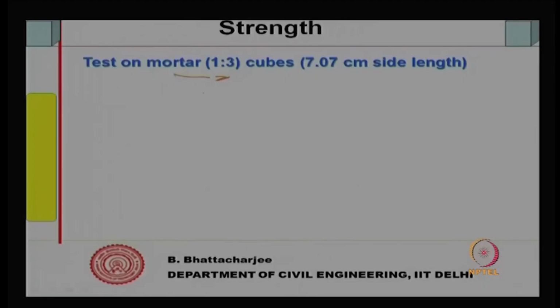So, what do we do? We test mortar cubes for compressive strength. We use a test on mortar 1:3, 1 cement, 3 sand, and this sand is standardized.